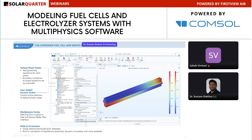So now we can see all the modeling steps available here, and the physics responsible for the applications. We have the hydrogen fuel cells where you can define the H2 gas diffusion electrode, or H2 gas flow channels, and the membrane. So now you can have all five functional layers, and some additional physics, let's say free and porous media flow for both sides, and the coupling of the fundamental study like fuel cells and the flow studies, which will be coupled by using these reacting flow techniques.